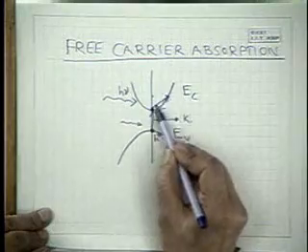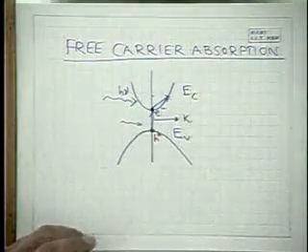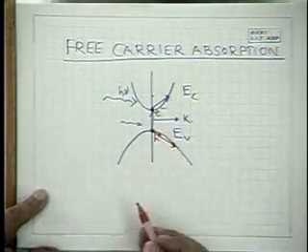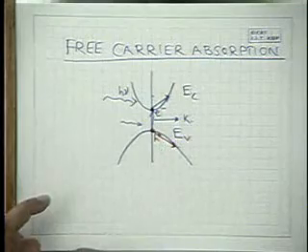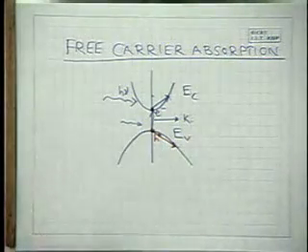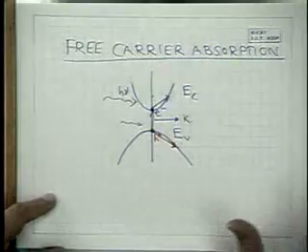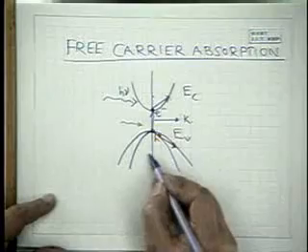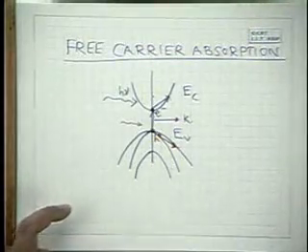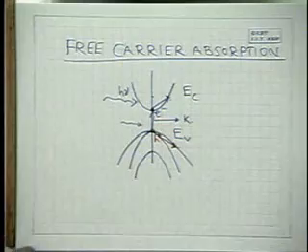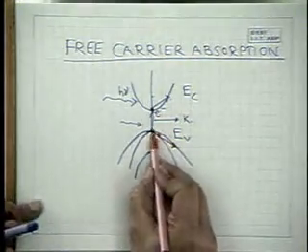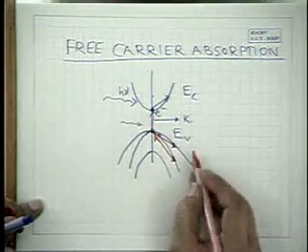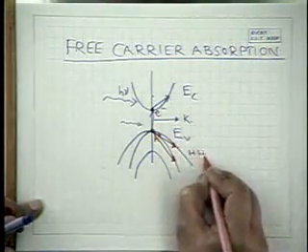But here, if you have excitation of electrons from a low energy state to a high energy state, or holes, change of k vector is involved, and obviously this involves scattering either due to impurities or phonons. If you fill in the total valence band structure, one can get free carrier absorption of this type either in the heavy hole band or the light hole band.